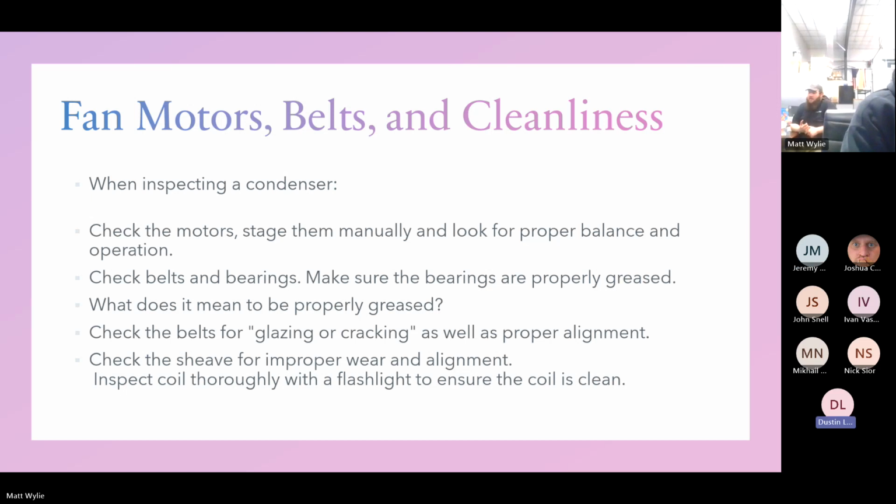Yeah, I think the old style was like a timer where it would energize the solenoid and dump a certain amount in and then check the temperature again. But everything switched to the expansion valve style. If I recall right, the one that Joel and whoever did at Flying J, they had the old style on the old compressor. So one of the questions was, I've got this solenoid, but now I have this expansion valve, where do I put it and what direction does it go in? And it's just a compressor safety type thing.